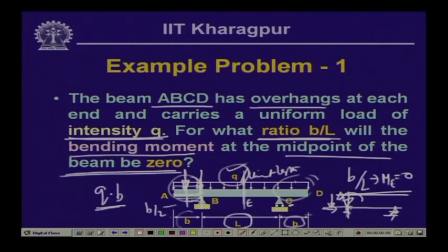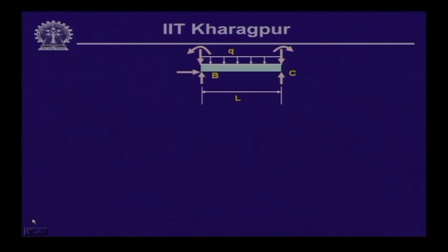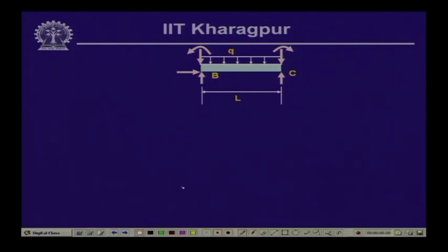And similarly, if we transfer this concentrated force over here at this support, we will have a concentrated force, and then this is going to cause a clockwise moment at this point. So, if we make a reduced form of this particular diagram, it will be something like this, wherein you see that we have now replaced the hinge support with the reactive forces, which let us call R b and H b. Let us call this reactive force R c, and this is being roller.